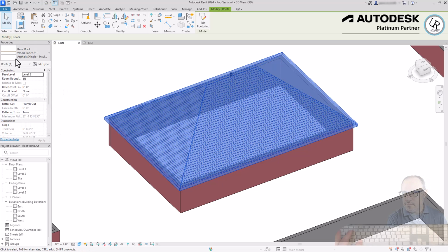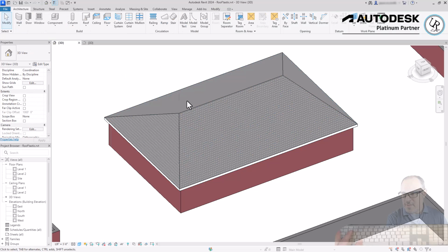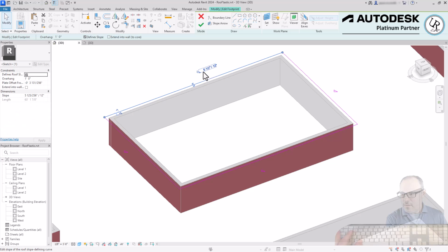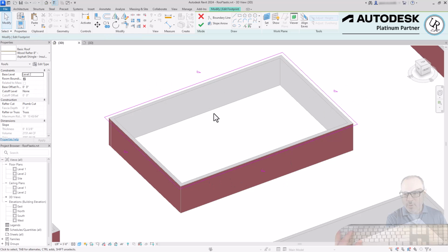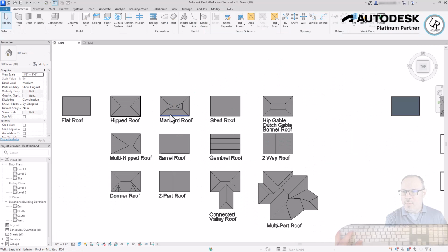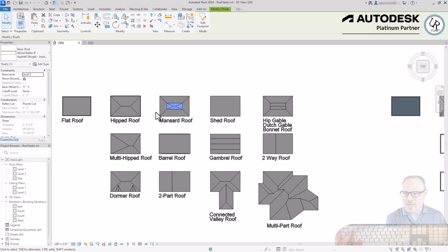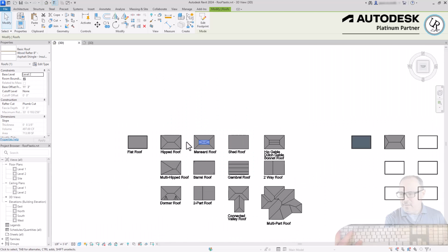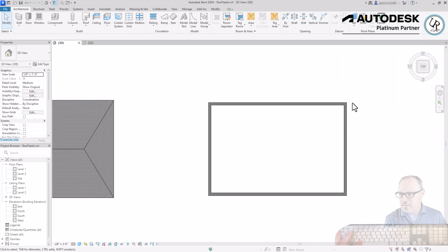If I look at the properties of the roof now, it's not showing me right now, but if I double click on the roof to edit the roof again, you'll now see that the roof slope says 5.5 inch by 12 inch pitch. 9, 12, 5.5 inch by 12, and 9 and 12. So as you're moving that grip, the roof slope is actually changing, making them uneven, at least on the same sides. Next, we'll look at a mansard roof, which is a roof on top of another roof that have different height conditions. And it involves a little bit more complexity, so we'll look at that.